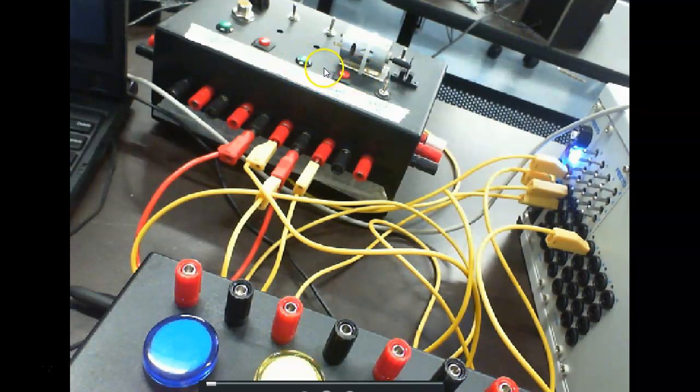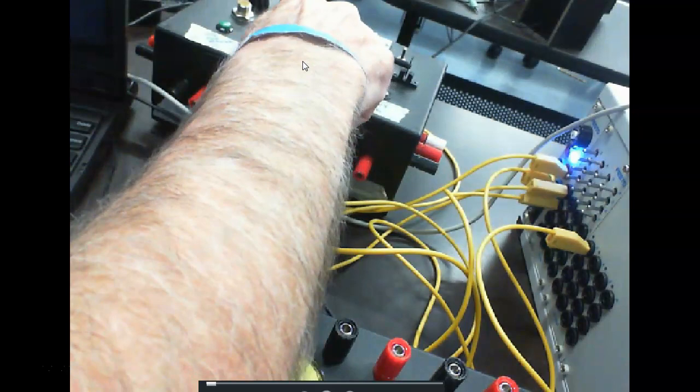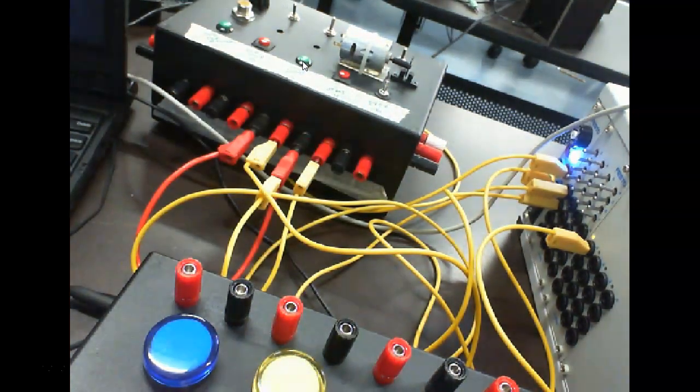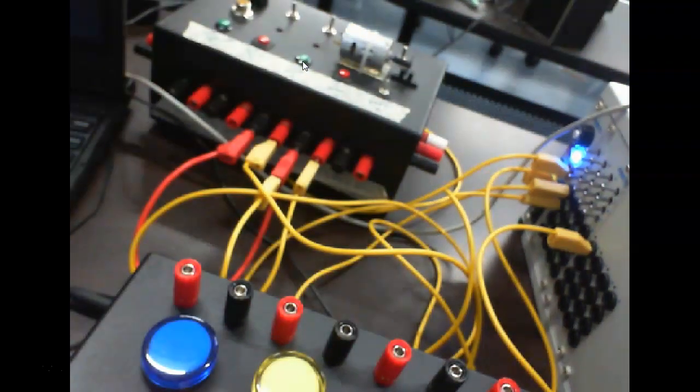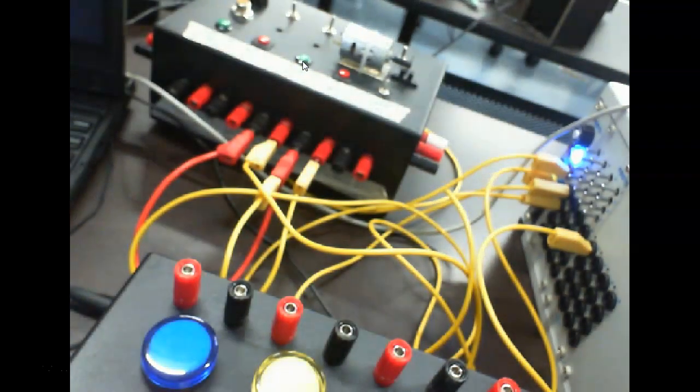I'm using normally open. This is my start button. I'm going to press it, and it starts. So I've got that motor hooked up to that output. Even though that coil in there is not real, it's a program coil. If I assign it to that output, when that thing goes through, that output comes up. And this is my stop button. It's a normally open stop button because I'm saying it's true if it's open.